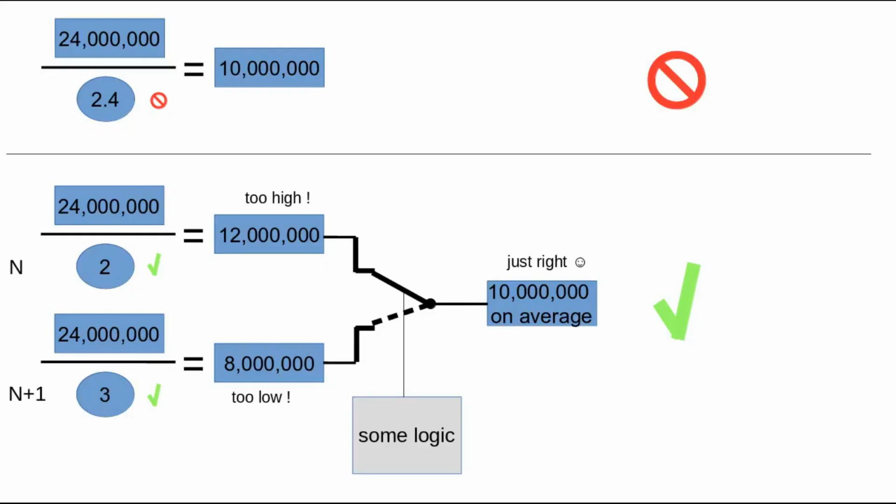We want, for example, 10 MHz out of 24 MHz, which needs a divisor of 2.4, which we can't do because we can't do fractions. So what we do is the next best thing and get the 2 closest frequencies instead by dividing by 2 and 3. Both are whole numbers and therefore okay.